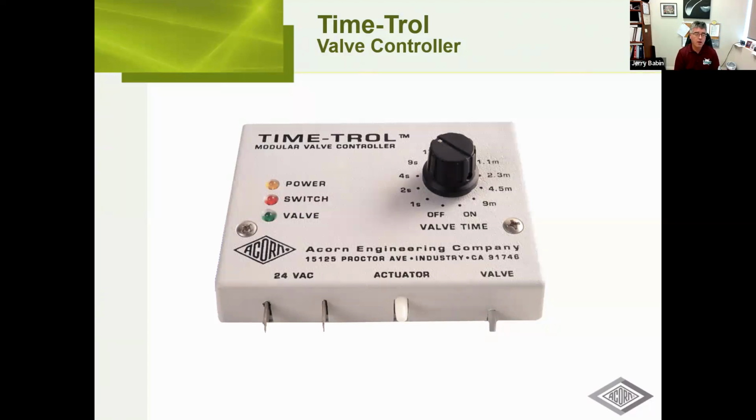And again, these take 120 volt power going to the controller, and then low voltage going back to the solenoid valve. You'll see there's actually a connector for the push button. Your air activation using an Air-Trol metering valve would be connected to that as well. This could also be set up for toilets and also have the cycle interrupt as part of the package.